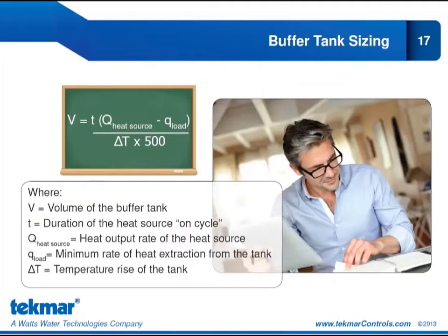Now, how do we size the buffer tank? It's actually pretty straightforward to size. We have the formula written on this slide right here. So it's based on 4 variables. The first one is the duration of the heating or cooling source on time. So this is this small t here. Now typically we're looking at 5 or 10 minutes for heat pumps.